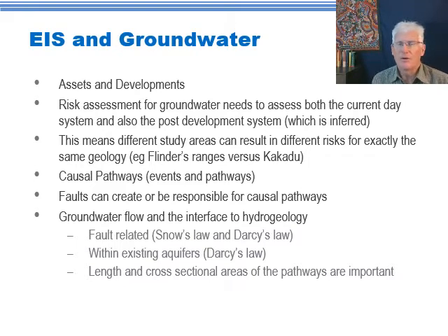So one thing that wasn't obvious to us at the beginning, but has become really clear, is that actual risk assessment for groundwater needs to assess both the current day or the pre-development system and then the post-development system. And then of course you're not going to be able to make direct measurements on the post-development system, so you need to infer it.